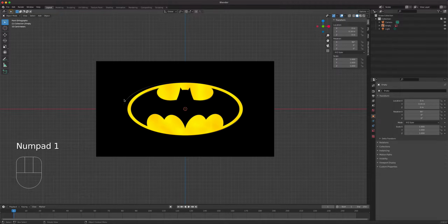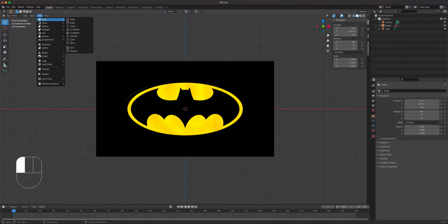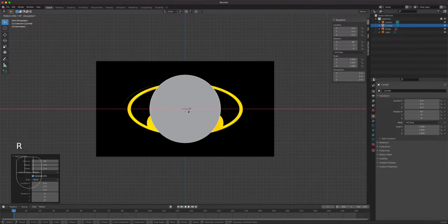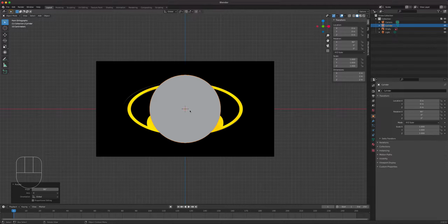Next we want to make this kind of cylinder. I know it tapers a little bit here, so let's simplify the model where this thing is actually all equal in thickness right here. So I'm going to add a mesh cylinder. The default on the cylinder is 32. We want to make this 64, so it's high poly in a way. It's still low poly, but we can make sure it looks smooth with auto smooth. So we want to rotate this.